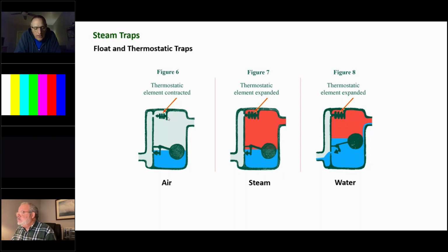Again, with old gravity steam systems, the boilers that were in those systems were these huge American Standard or Red Flash, or there's all kinds of different manufacturers from the 40s and 50s, and those steam chests were huge. And in some of them, you could probably fit a small current today's boiler inside the steam chest of the old boiler. So they didn't have any issues with extra water coming back. That steam chest could handle it.